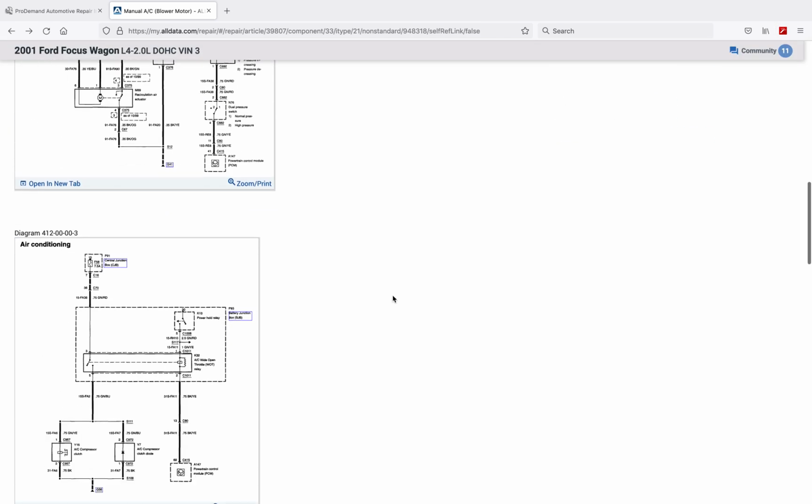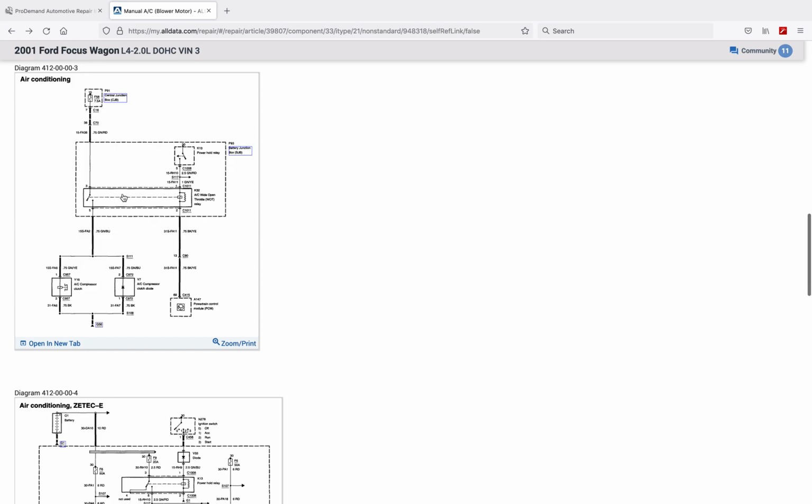All right, now down here I've also got another diagram, includes the output for my AC compressor clutch down here. Again, if it's an electrical component in the diagram, this AC compressor clutch connector 957 has 2 pins. 0.75 millimeters squared, green with a yellow wire is the power supply feed for the AC compressor clutch, and we've got a 0.75 millimeters squared black wire that's going to be the ground supply for the clutch.